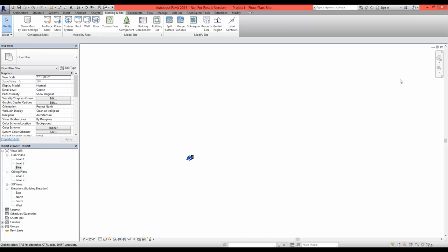It will show up as though it's imported, and it will show up as though it lives within this file, but we will not be able to see it from any of our views that we have within our model. In that case, we need to go into the civil model and actually redefine the origin point or redefine the way that we import that information. And at this point, you would definitely want to coordinate more with your civil department to make sure that everything is being done properly and that our real-world coordinates are not being lost.